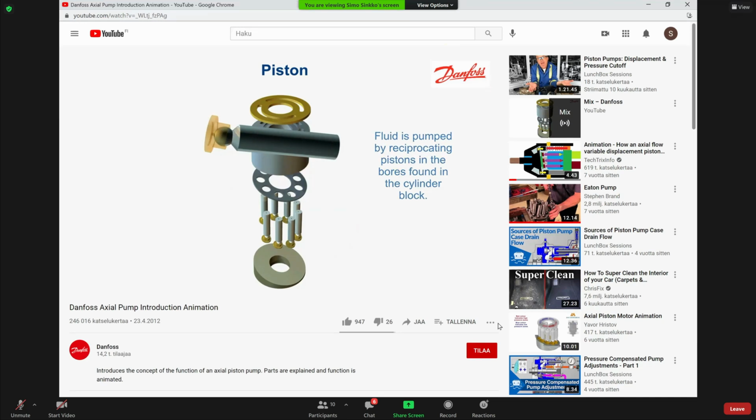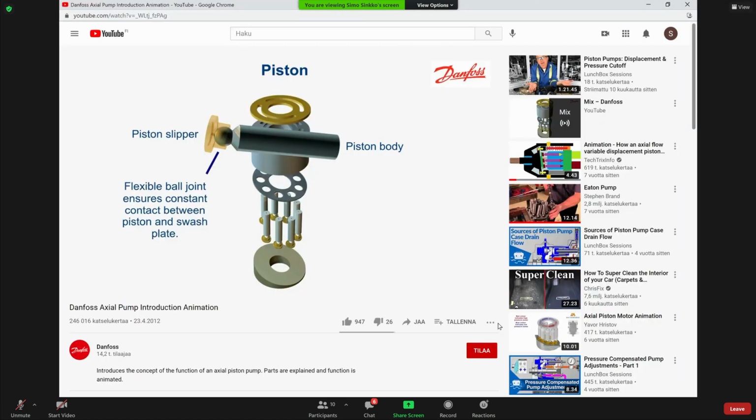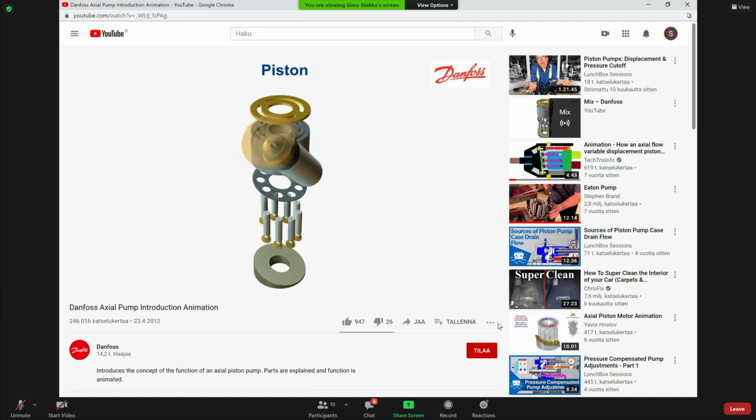And now we get back to the conversation that we had yesterday, about why this kind of hydrostatic transmission in some mobile forest tractors or excavators is so easy. It's because it's so easy to control this kind of pump, and like I mentioned, it gives you very high forces easily, but of course the efficiency is not as good as with normal mechanical transmissions. But this is the unit they use to control the driving speed.